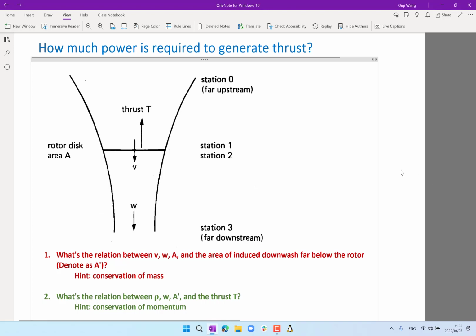So I'd like you to figure out a very, very simple scenario, even without considering the helicopter as individual blades, right? Just think about the blade revolving around the disk as a single device that continuously generates a push on the air as the air goes through this rotor disk. So basically, ignore this unsteady motion of the blades and just think of the rotor as a blurred disk, right? Imagine that the rotor rotates so fast that even the air wouldn't see the individual blades.